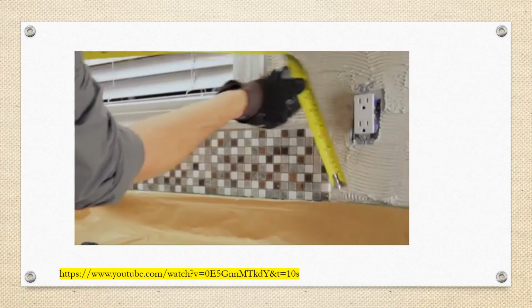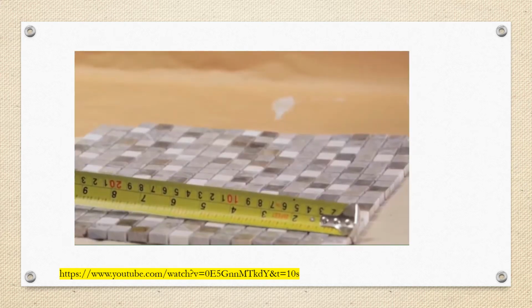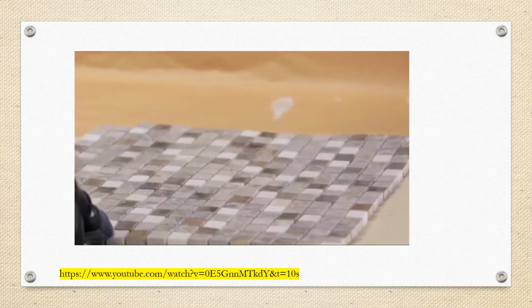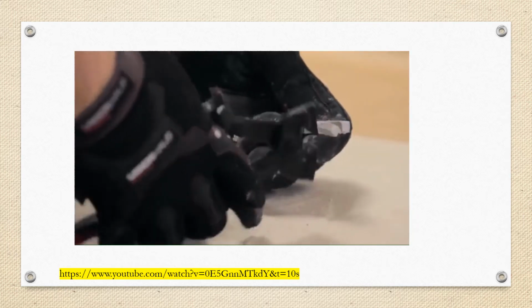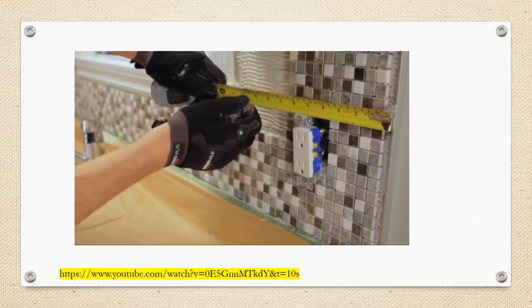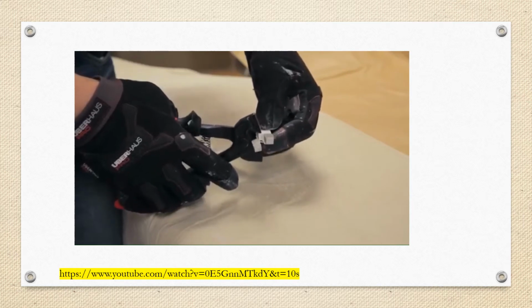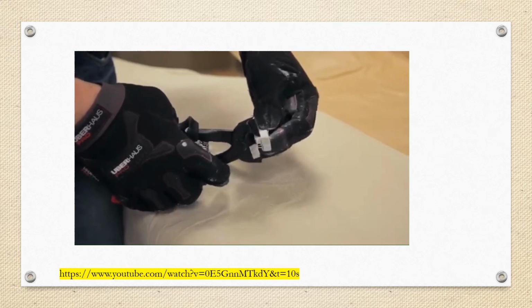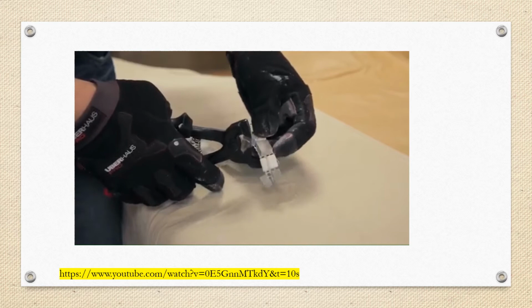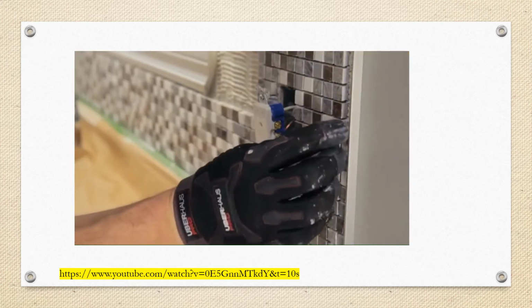To work around electrical outlets, cabinets, or other objects, take the necessary measurements for the cut. Then, use a tile nipping tool, a grinder, or a wet saw. To install individual pieces of mosaic tile, measure the space to cover, then cut individual tiles from a sheet. If needed, wet the surface of the tile and cut to size with the tile nipping tool. Apply adhesive on the back of the tile piece and press in place.